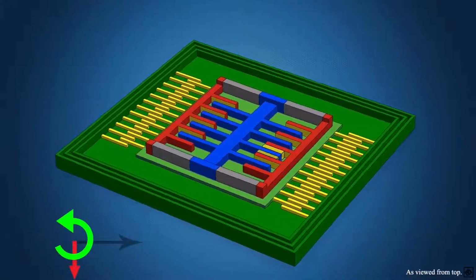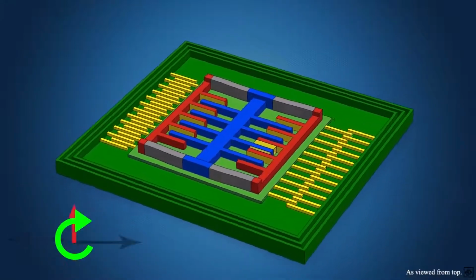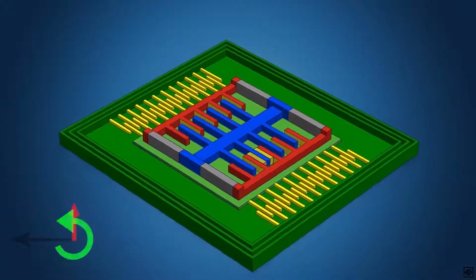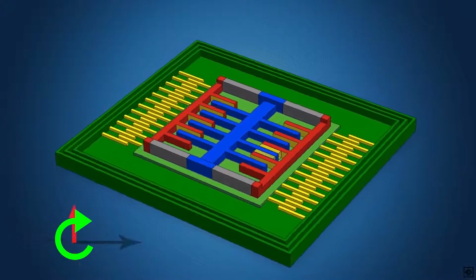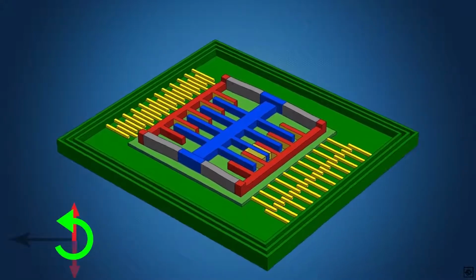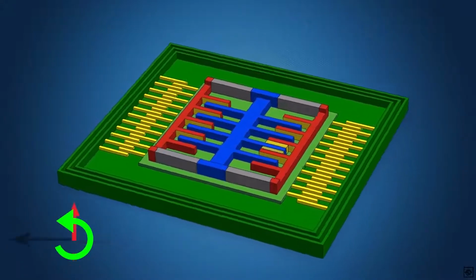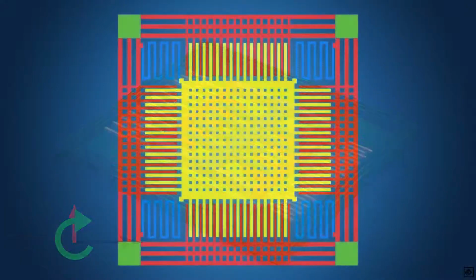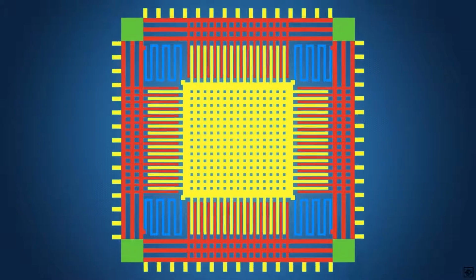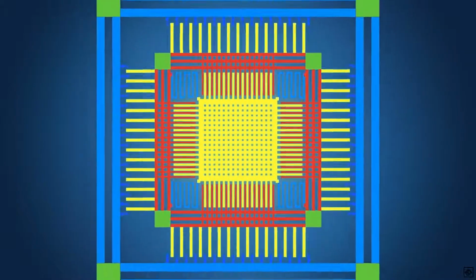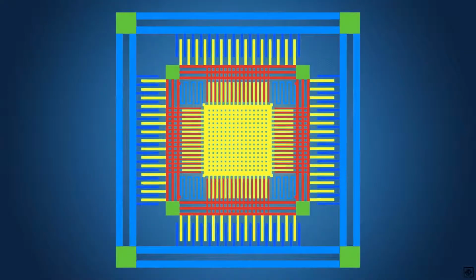This accelerometer can detect acceleration in 2 directions, and so can the gyroscope. Both the rotations are perpendicular to the linear motion of the accelerometer. Rotations in the axis parallel to the motion axis will not show the Coriolis effect. To scale this to the third direction, we oscillate a 3-axis accelerometer in 2 directions, or in a plane. Its microstructure looks like this. This can detect rotations in all 3 directions.